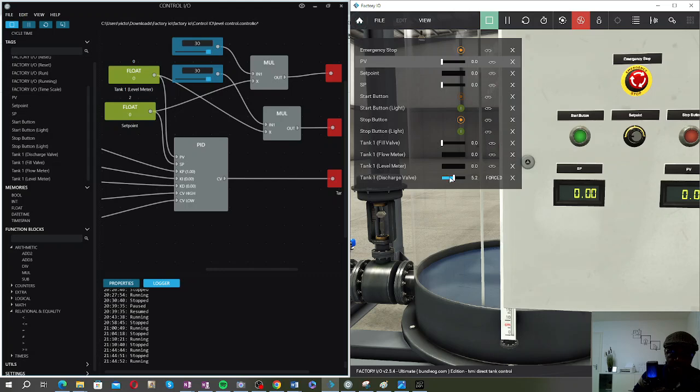Now, if I close the discharge valve, you can see this is also a 0 to 10 volts signal. So that's why I'm saying 0 to 10 volts here. The level to which I open it affects how much this valve is opened. If I open it a little, you can see. So I left this open so that I can monitor and see how well the controller is working. So that is that. Now this is the set point.